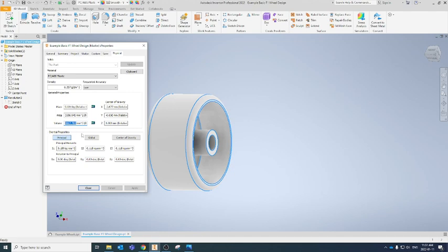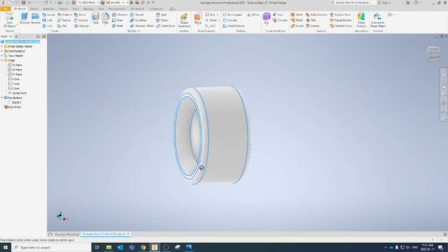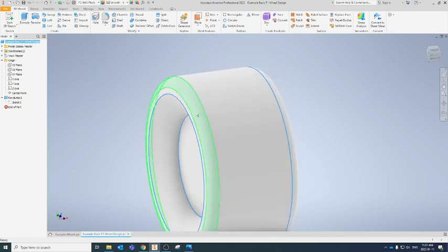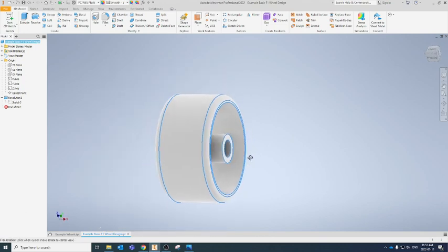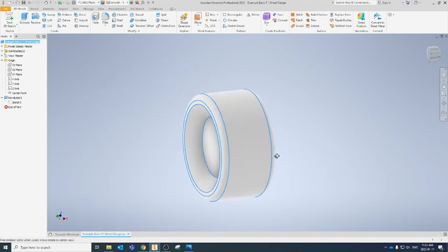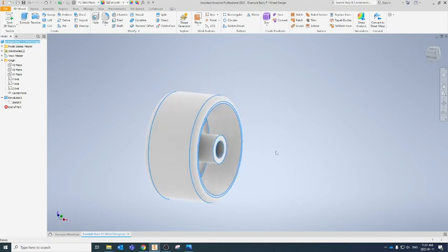So we've cut this down quite a bit, and we could continue trimming this, maybe by doing smaller fillets, by doing a steeper angle here, by making these walls, these shell walls here, a little bit thinner. So you can continue to refine this, making sure though, of course, that your wheel is still strong enough to support your car up and down the track.